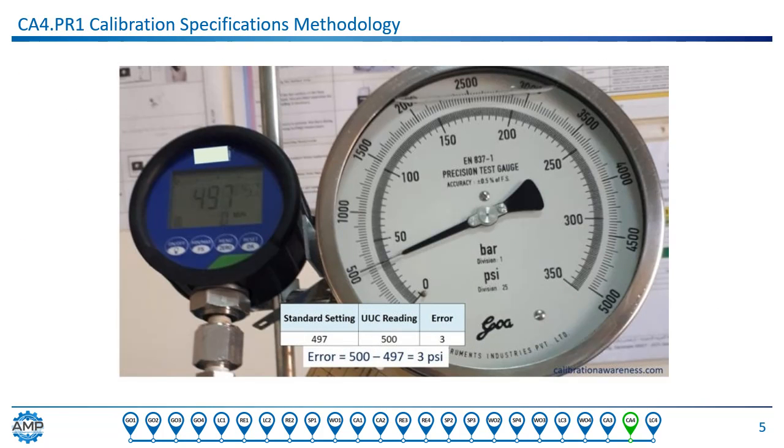Calibration specifications provide a process for the way an organization approaches calibration execution by defining rules for the information necessary to perform calibration. Common information found in a calibration specification includes instructions on how to perform the calibration, how often the calibration is performed, values that are going to be tested, the acceptance tolerance for the calibration, as-found documentation and as-left documentation, and the pass-fail indications for the calibration.